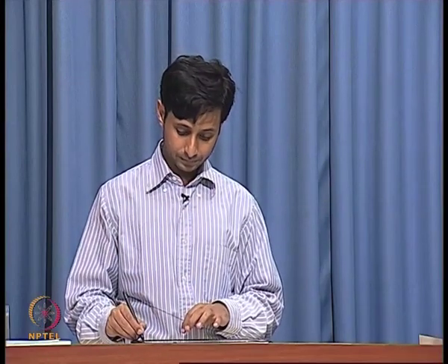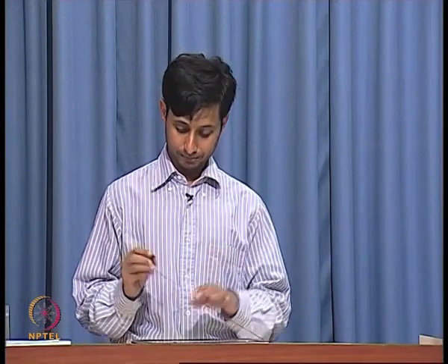If I launch current I in from the source, I is not going to reach the load, some of it is going to leak out through the capacitors, through the conductances. Similarly, if I put a voltage V across the transmission line on the source side, I am not necessarily going to see V on the load side, some of that voltage is going to drop across the inductors or across the resistors, right. That is number 1, that is what we saw.